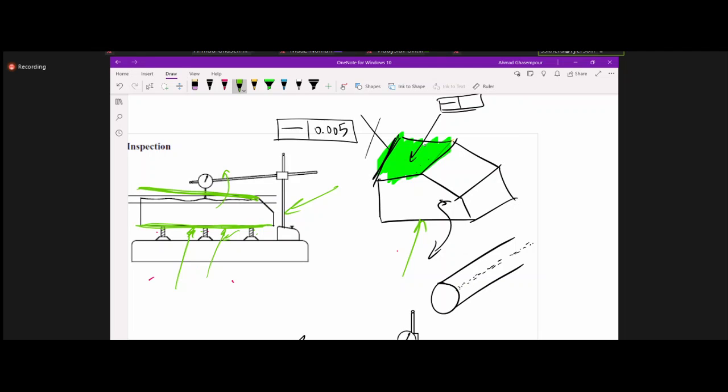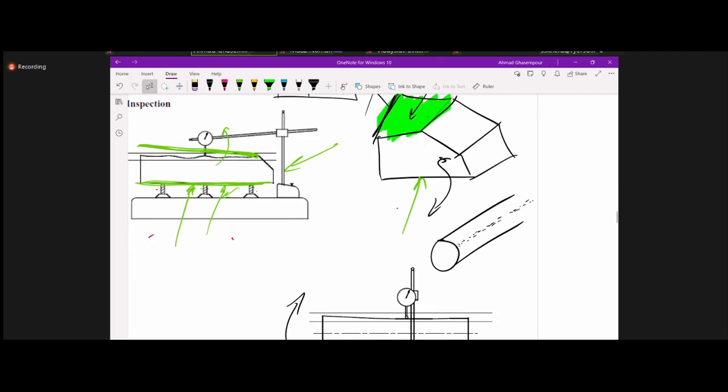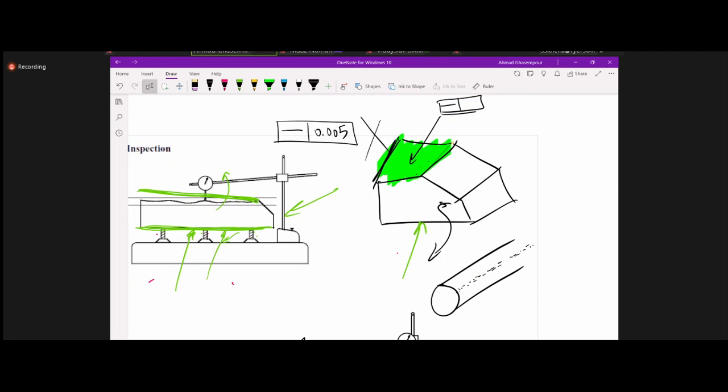But in general, it's not an easy task, and that's why when we get to that point, it's not a good tolerance to use, especially without M. So it's a good tolerance to use with pins and cylindrical objects if it has that M in it. We haven't talked about when you decide to have M or not M. We'll get there, but if you see this tolerance without M, you may want to talk to whoever put the drawing together and see whether that's really needed, because it makes a huge difference in inspection cost.